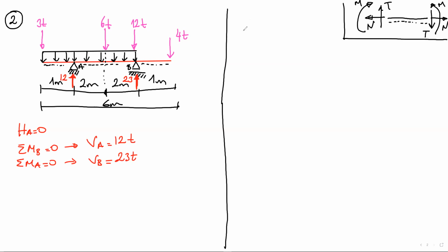Now, to draw the shear force diagram, we need to know the first point's shear force. You can see it directly, or if you can't, don't hesitate to cut the structural system. I'm going to cut the system so close to this point. Let me draw a sketch for it.